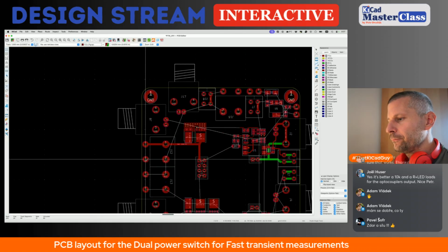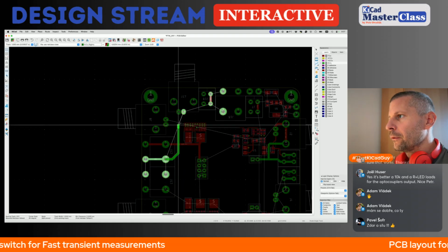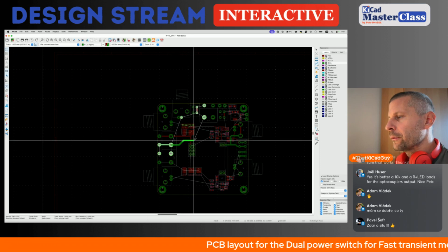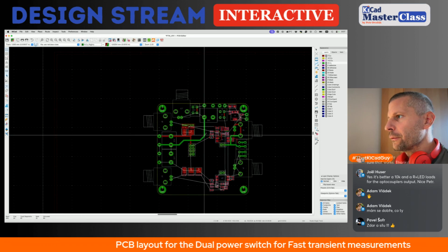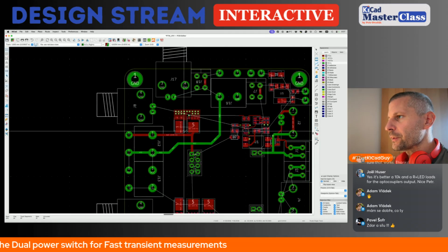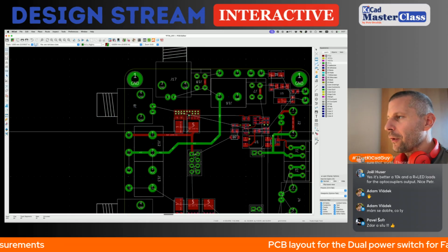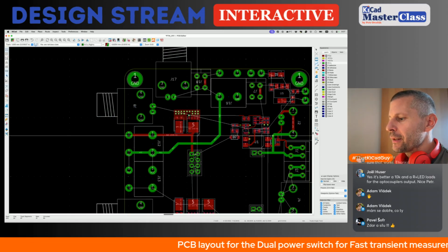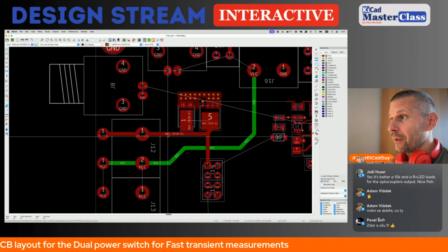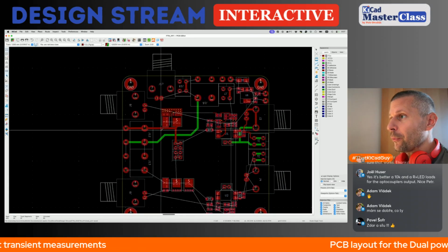This will be on the bottom. No, not here, not through here. Probably through here. Yes. This is the small or light load MOSFET, so the polygon will be below because the cooling capability can be lower. Okay. These tracks are only like auxiliary to see, to help me imagine where the polygons will be placed.